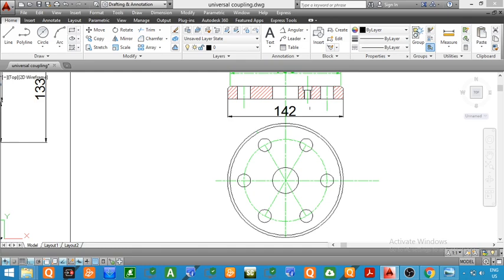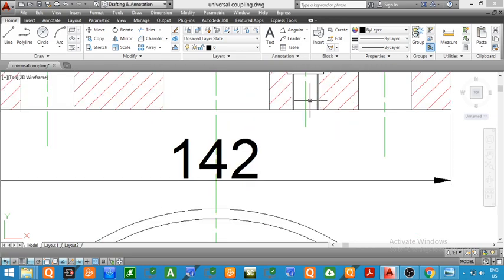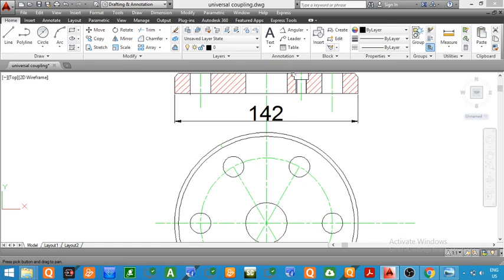Now in the next step we have to draw the top view of this hole, that is this hole which is provided for providing a seat for the head of the cap screw and internal threading which is provided at the bottom portion. So now we will draw the top view. The top view of this cylindrical hole will be a circle.